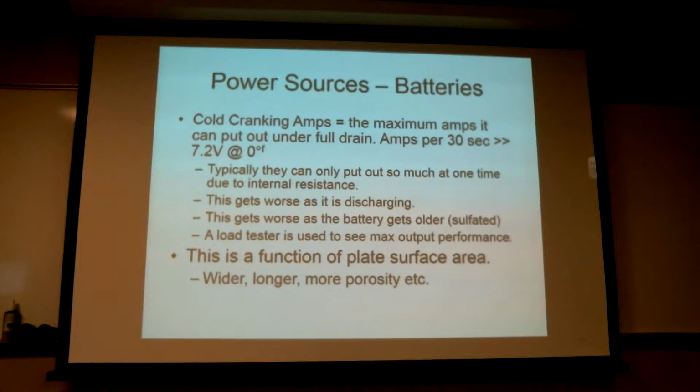Whatever you use, when you dead short the battery, it's going to get hot. So it's better to use a tool that has a big heating element contained in a safe box. And in parallel, you're going to put a voltmeter there. And you're going to hook it up, 1, 2, 3, 4, 5, 6, 7, 8, 9, 10. Does it go down into the red?